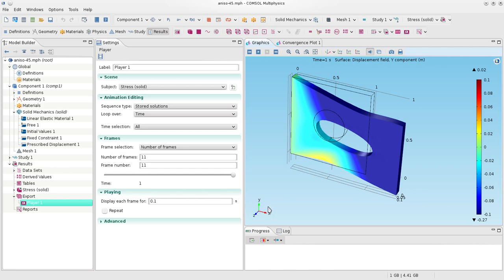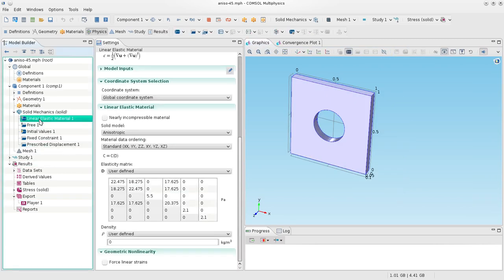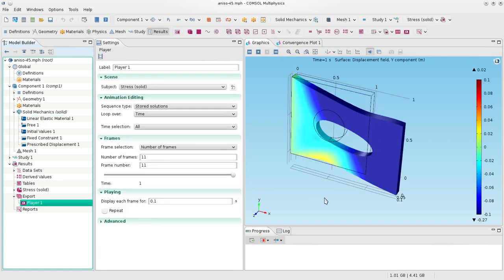And the way to characterize all of that effect is through the consideration of anisotropy, and we can easily do so. For instance, even in this scenario, I know there are 9 independent constants, but I go ahead and calculate the compliance or stiffness matrix in this case in its full glory, and I'm able to extract the correct solution from the problem. Okay, so that is the advantage of being able to work in a full anisotropic scenario, and that is what normal shear coupling physically corresponds to.